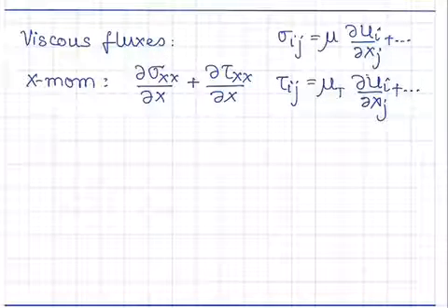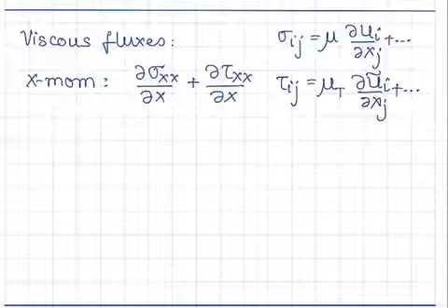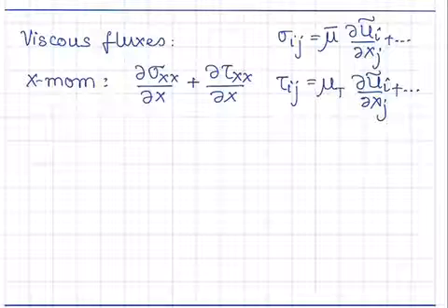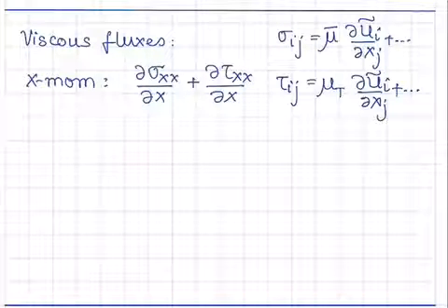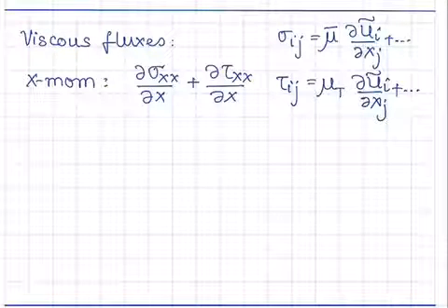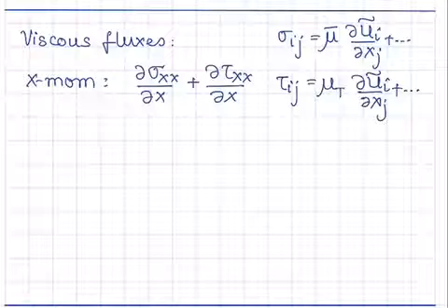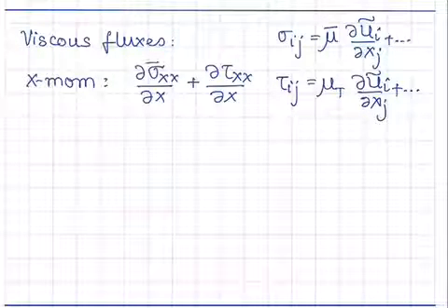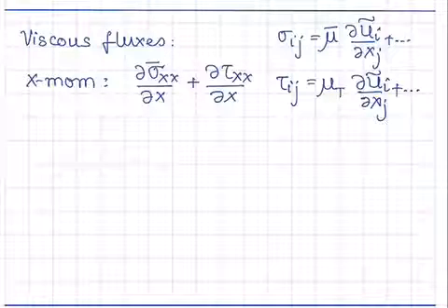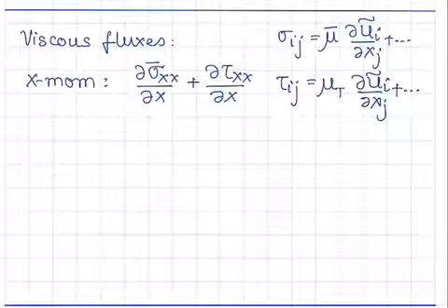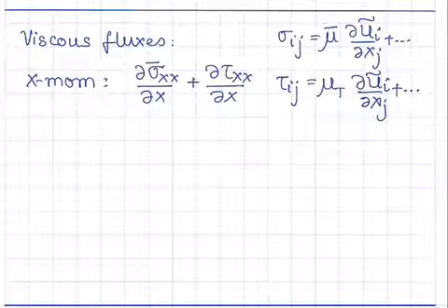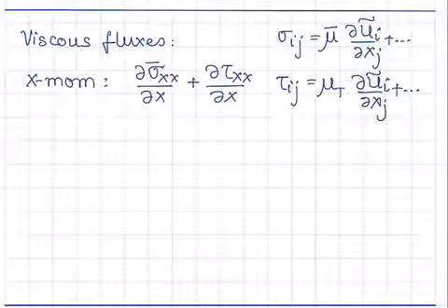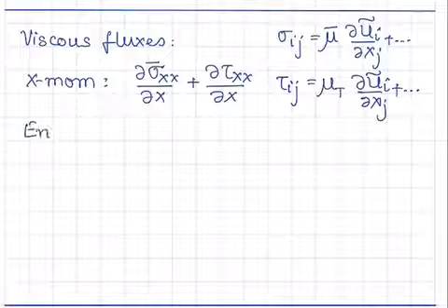The only difference now is that we have u tilde instead of u, and mu is a mean quantity, mu bar. It turns out that eddy viscosity is always a mean quantity. We don't necessarily put a bar on top of it. So let me place sigma bar, which is the mean viscous stress, and have the Reynolds stress term along with it. The energy equation